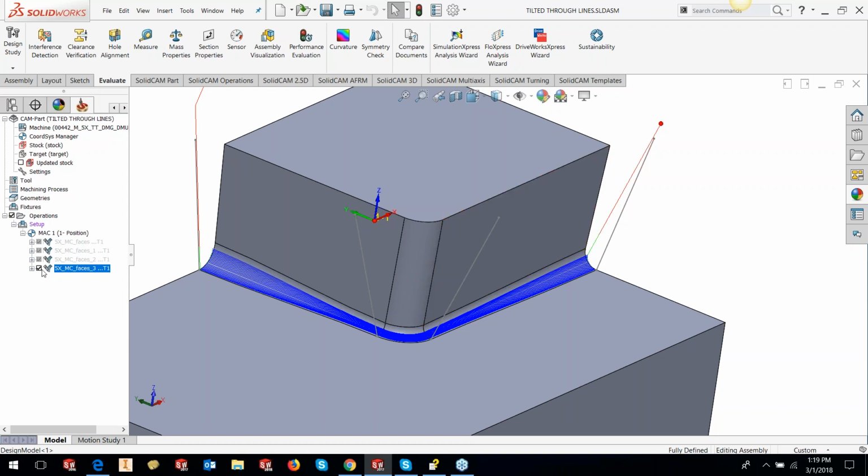Let's move to another very important subject of gouge check. Now, in gouge check, like I said, you have two functionalities. One is actually avoiding collisions, and two is using those avoided collisions to machine actually a surface. Okay, it's a tricky thing, but it's a very, very important and a useful feature. Okay,